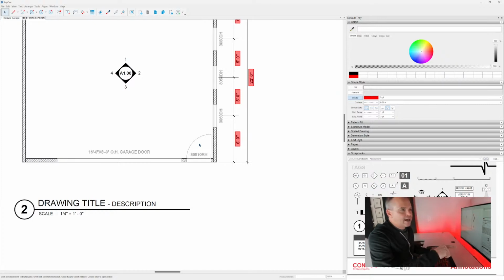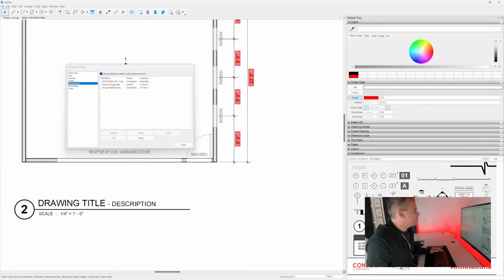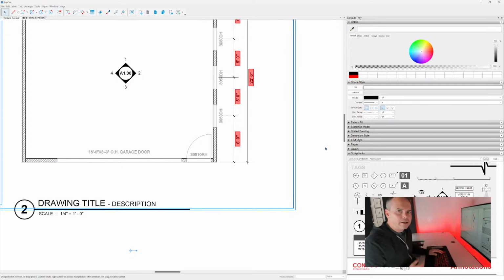I can tell you that using that live sync scenario drastically saves a ton of time, because I found that every time I go to File, Document Setup, References, and click that, especially when your references get a little heavy, it chokes and has to think about that for a moment. So I find that this live sync is one of my performance tips. That's going to be in, I believe, the next live stream and series of videos, which is how to speed up SketchUp and LayOut. Basically, how to speed up SketchUp for LayOut and how to speed up LayOut.